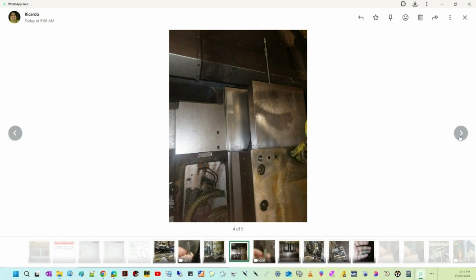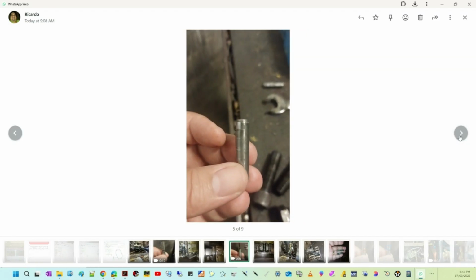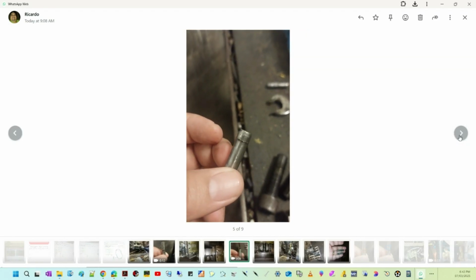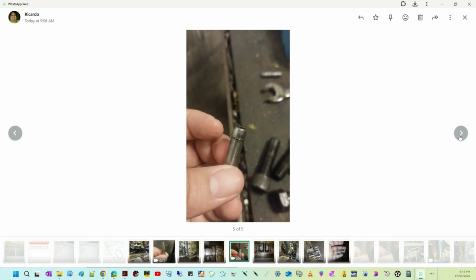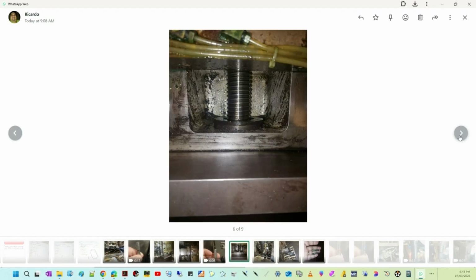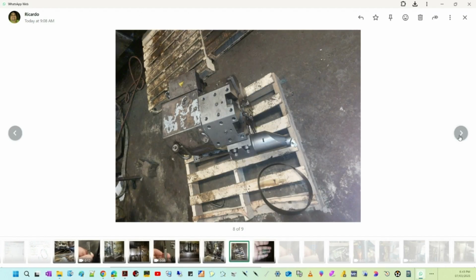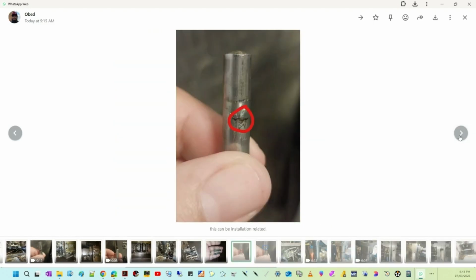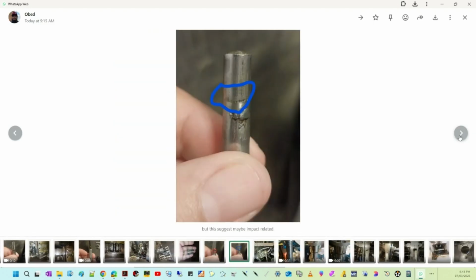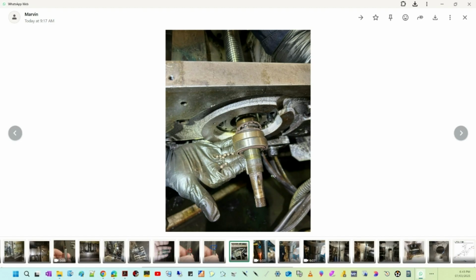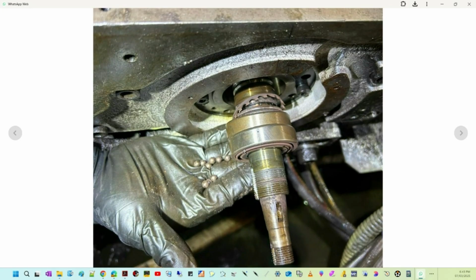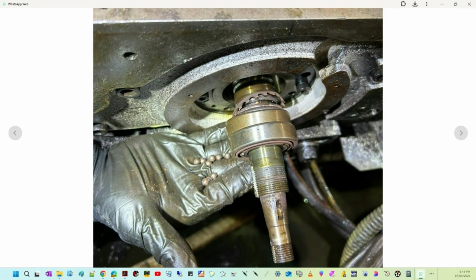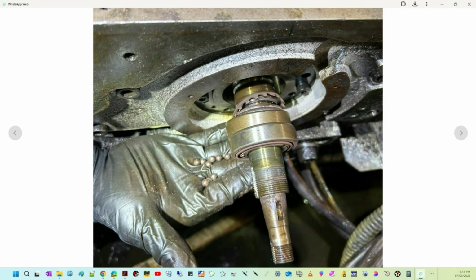And the bearings themselves. That was the big one. They found the bearings, specifically NSK 30TT62DB, which are high-precision angular contact thrust ball bearings, were completely destroyed. The report describes a complete failure of the bearing cage. The cage. What does that do? The cage is what holds the individual ball bearings in place, keeps them evenly spaced within the bearing races. Here, the cage was described as destroyed. The ball bearings were loose, just rattling around, and that almost certainly meant damage to the races, too. The tracks the balls run in. It was pretty catastrophic for the bearing.